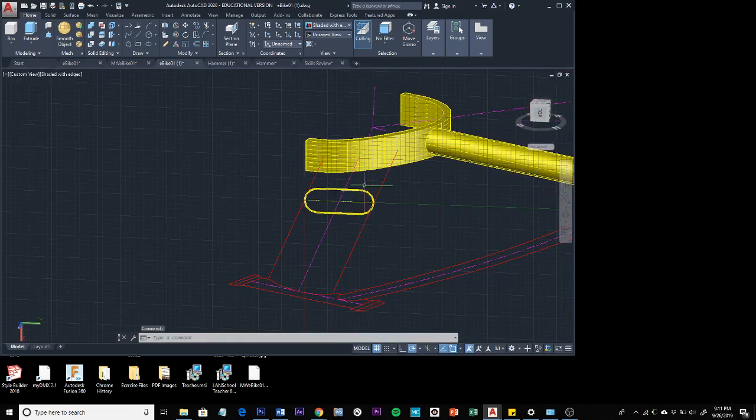And before we do that, I'm going to try to make this easier on us by moving this beyond the bracket first before we extrude it. That way we don't have to extrude it twice. So if we left it here, I'd have to extrude it this way and then use the face extrusion tool to extrude it this way. But we're just going to move it first and then extrude it one direction.